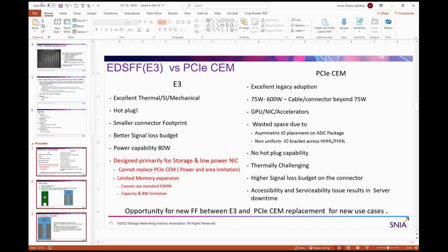So let's say one DIMM is fundamentally close to 20 watt today, 25 watt on DDR5, DDR6, and it will go to almost close to 25 within probably another 2 years. So imagine the controller is going to be at least 5 to 10 watt for the E3 type of thing I'm talking about, correct? So you are trying to expand those capacities on a per channel basis, and a 75 watt E3 is going to be extremely difficult from a capacity perspective. I see. That is the point we're trying to make.